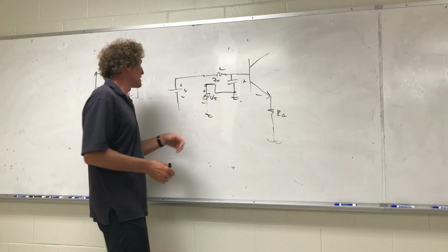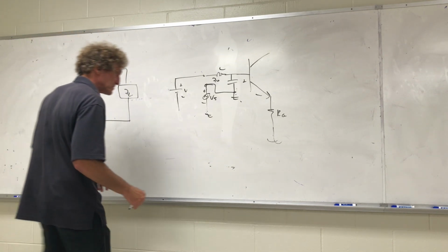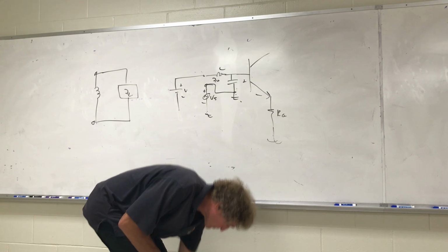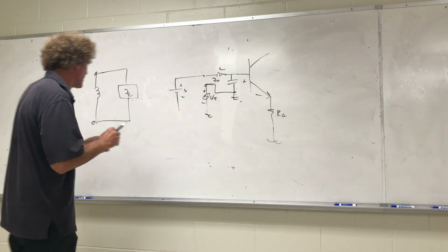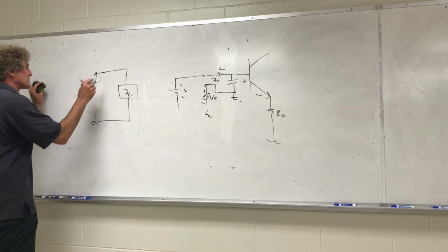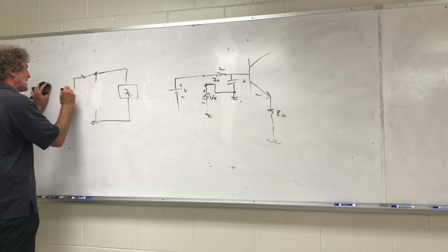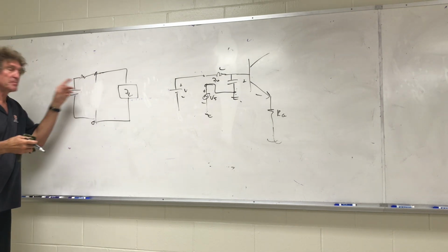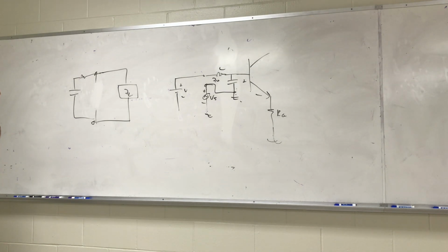Now, it could be either, there's two places you can locate it, obviously. You can locate it in series here, and then a capacitor here, but that requires you to be in the rotated Smith chart to use that configuration. Your ZL, when normalized, has to be inside the rotated one. Y'all with me? And then you get a capacitor.